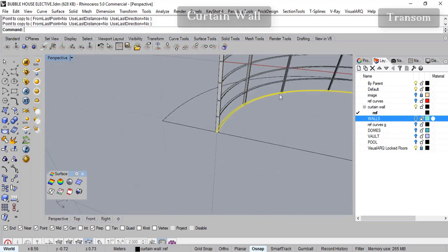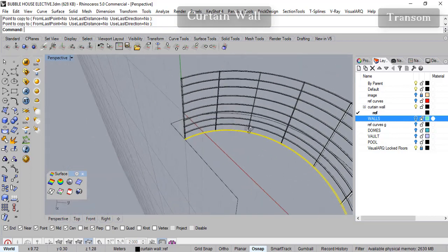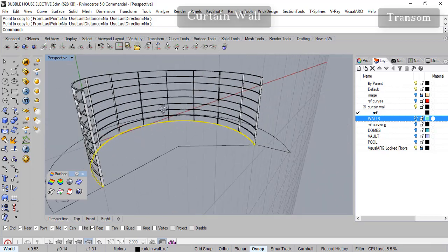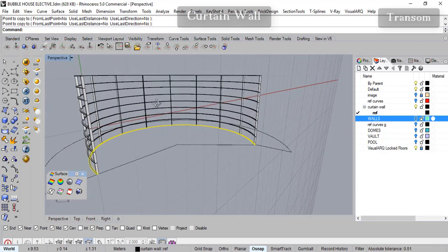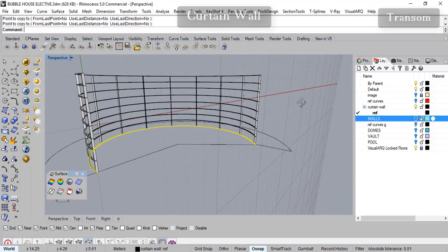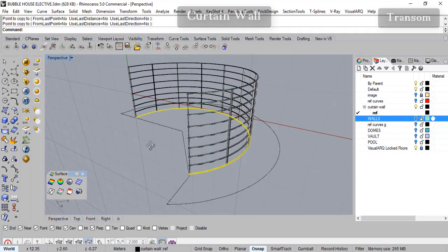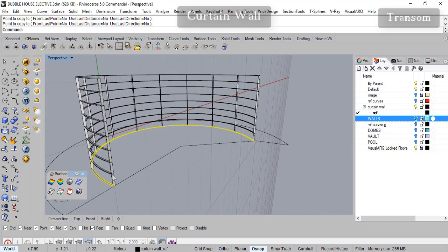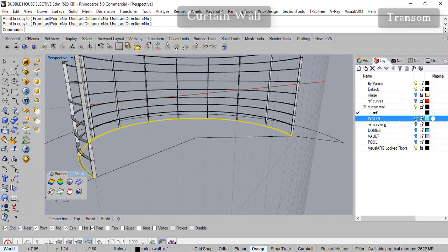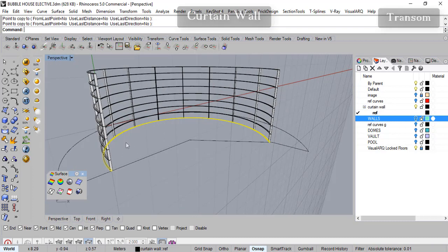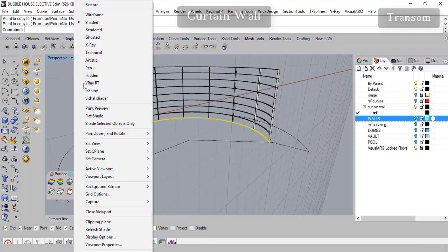So if you look at this, now you made so many copies. Okay, good. Now we might want to save this construction plane, because at a later date we might want to come back to this orientation of construction plane, so that we can then decide to reduce the number of the sash bars or change its profile or whatever. In this case it will not be required, but in any case I'll show you how to do it.